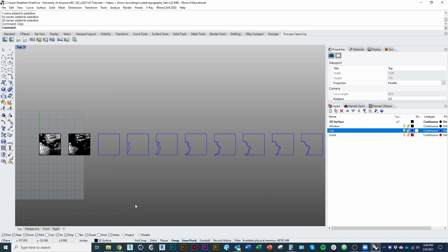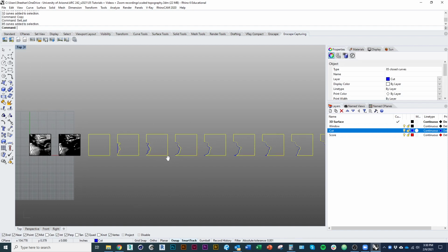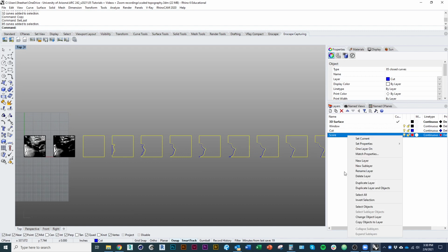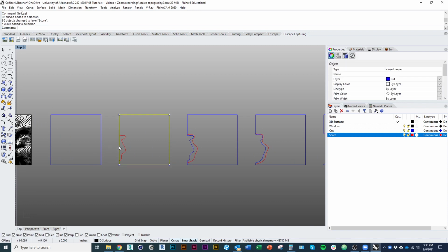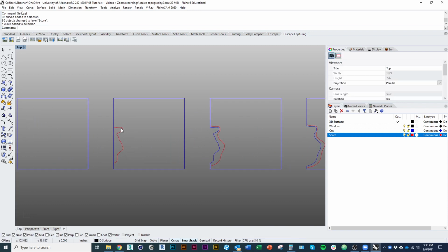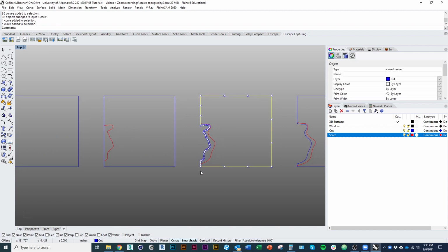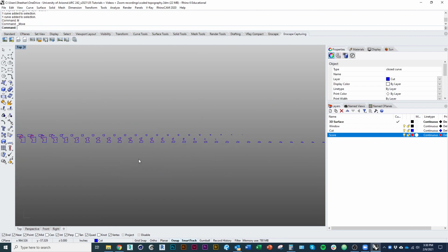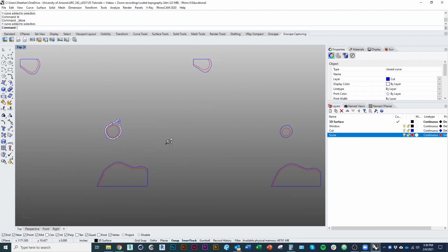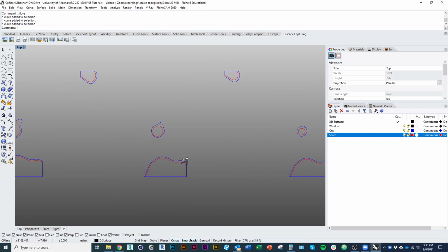Then I'll click to deselect, and before I do anything else, I'm going to type in select last. That selects the objects I just copied, and I'll move those to the layer score, change object. Now when I cut this piece out and score that line on it, I would end up with a scored mark on that piece that indicates exactly where that edge is supposed to line up. And when we get over into pieces like this, figuring out where that guy is lining up on that guy is going to be really helpful.